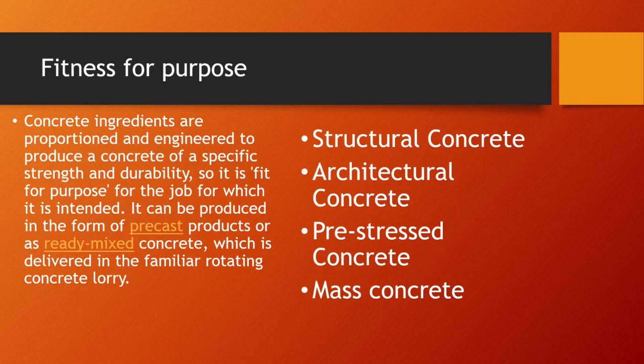So we've got the structural concrete, which of course is the real big bad boy concrete: beams and columns and slabs for foundations. This is the heavy duty structural concrete, typically a minimum C35 or a C50. Now the C is a classification for concrete, so C is concrete, and 35 would be 35 newtons per millimetre squared. So 35 newtons for every square millimetre. Okay.